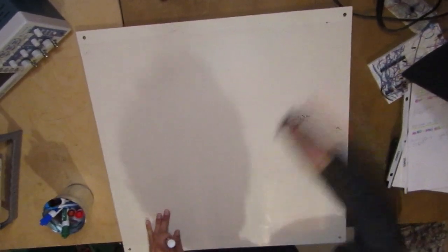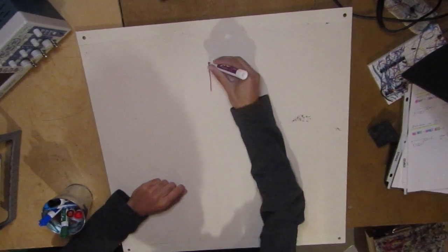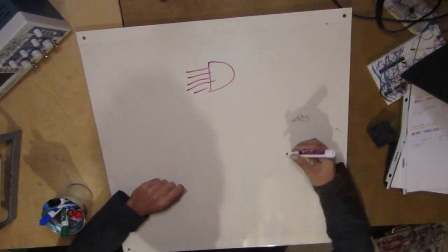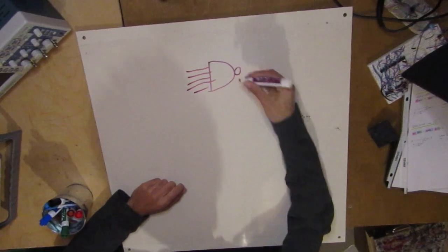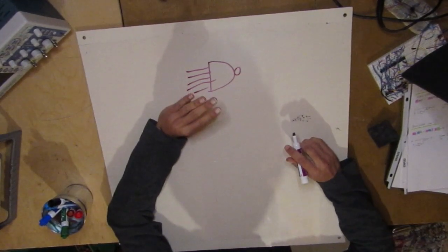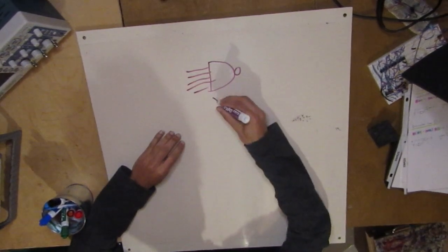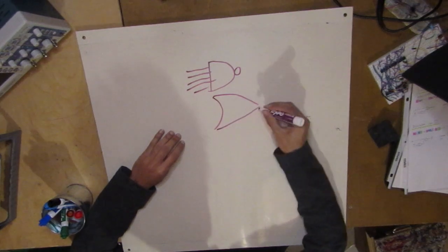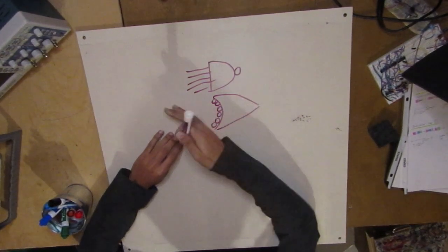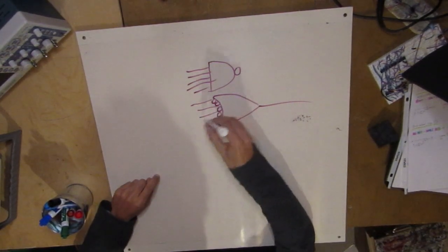Pretty cool. So for the chained AND gates, we just draw them as a big gate with multiple inputs coming in. And we could have the NAND version. So you could invert it, and it's going to be an OR gate. Remember, in the last video I explained De Morgan's theorem. This is the same thing as just a big OR gate. That's thinking of zeros as ones and ones as zeros. This is the same thing. And you get the multiple inputs coming in.